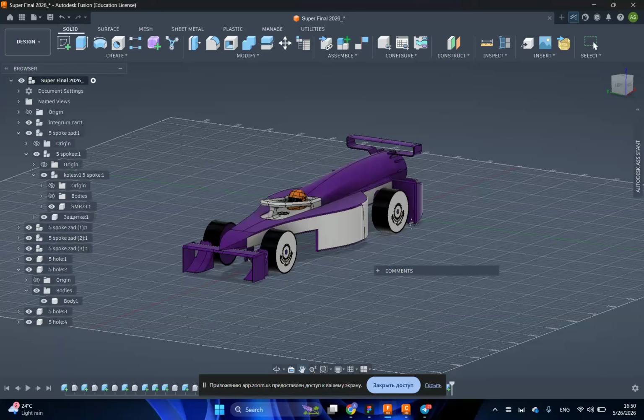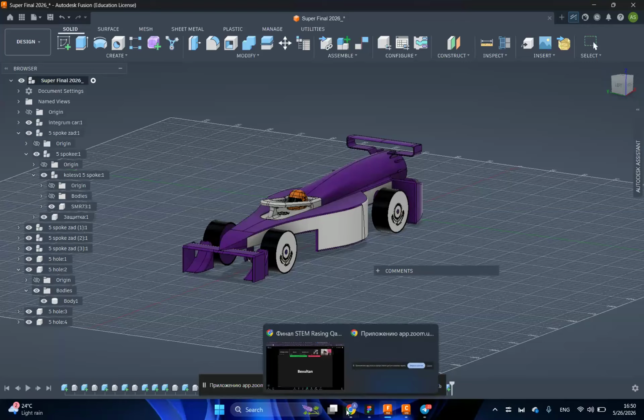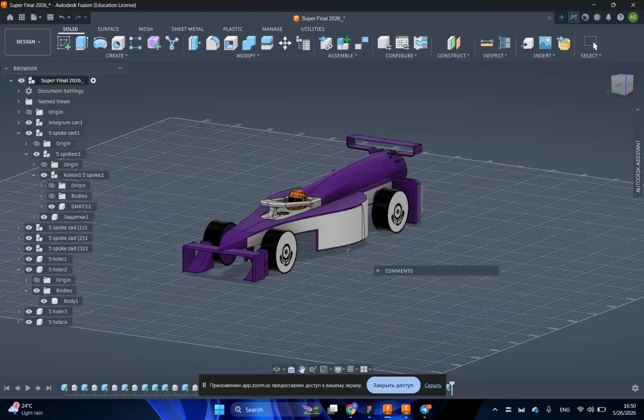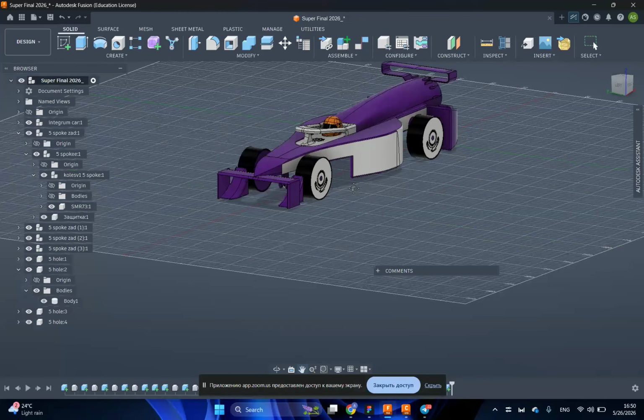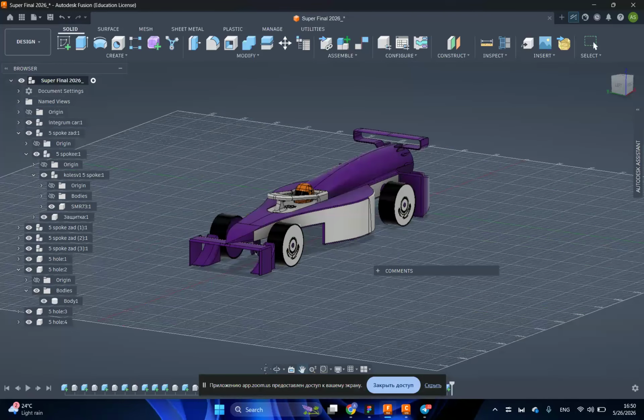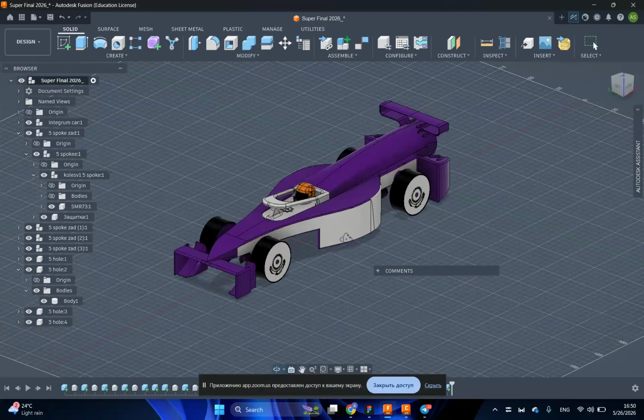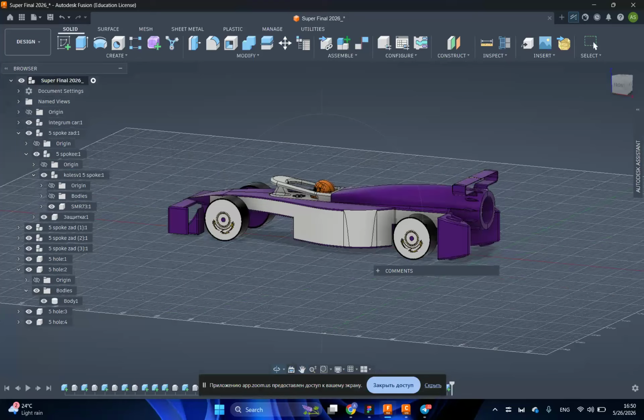Yeah, here's our model. So, okay, you can see like from our... Don't you see the car? No, we see. Comparing with the previous version, we have changed the nose cone, changed the teardrop body, changed the rear wing. So the air could stay on the car, not separate, because of the Coanda effect.